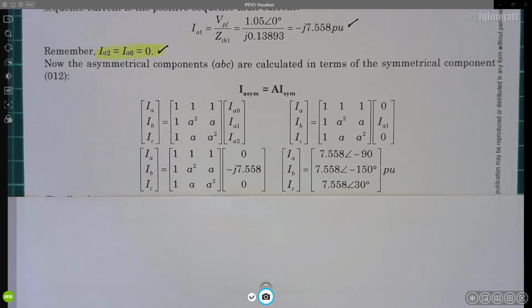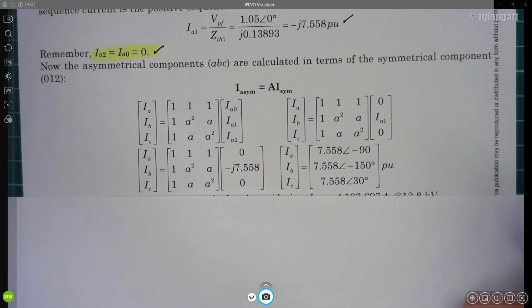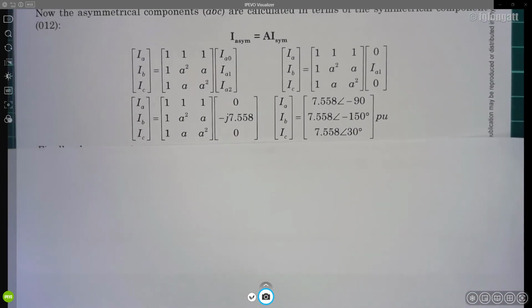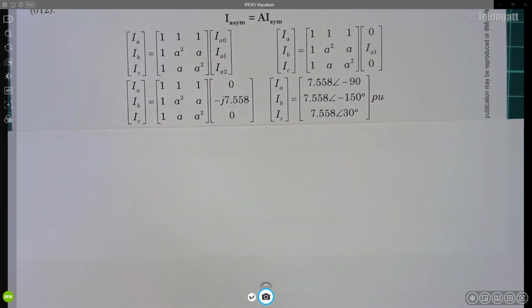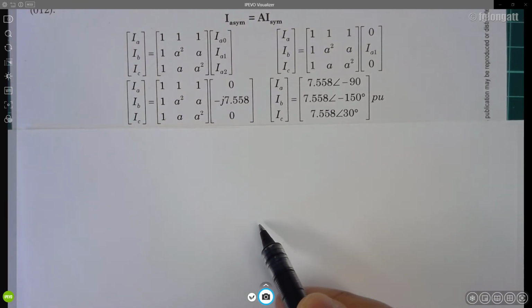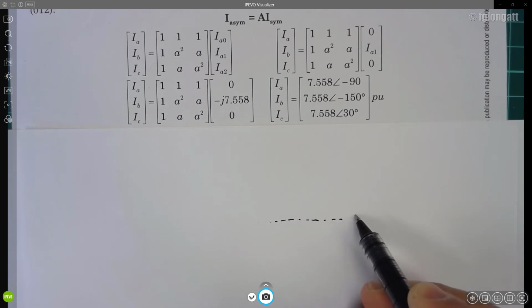Something that I want my students to understand is that those currents, those phasors, represent a three-phase system, in this case a balanced three-phase system. And also, they preserve this beautiful property coming from three-phase systems where we have 120 degrees apart between the phasors. If you allow me to use my ugly handwriting, we can say that the reference is here. Let's say this is 0 degrees.